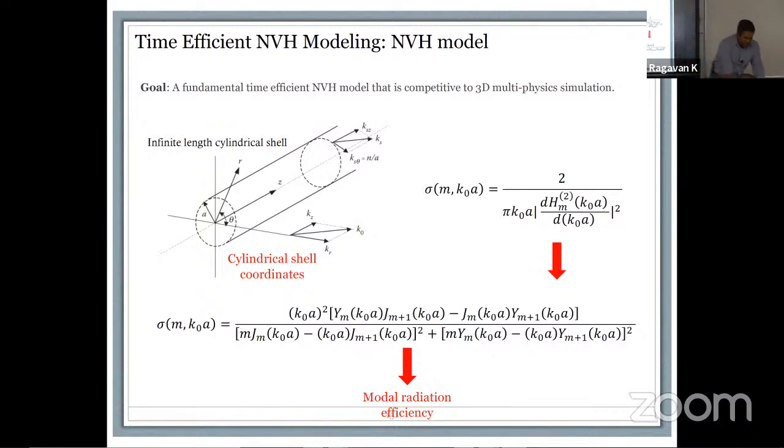And the reason for that really is because in our case, the only points of interest that we have are the circumferential modes of the stator. Which means that the forces of the order R that's given in this equation are only going to excite the mode that has this exact same order. So when you have a frequency excitation that is close to the natural frequency, your vibration will reach a maximum, and your excitation will then be observed.